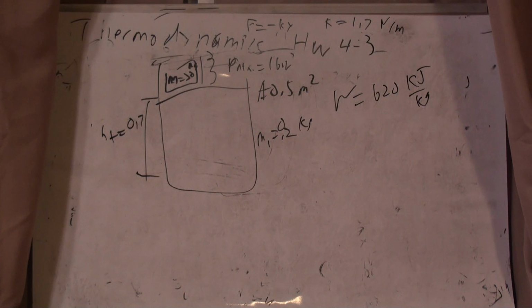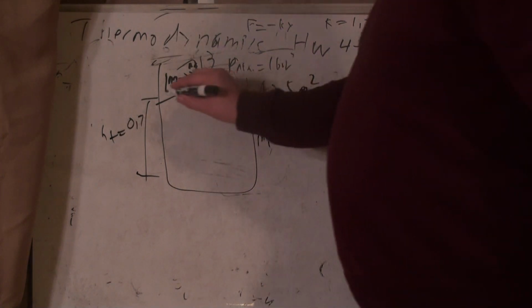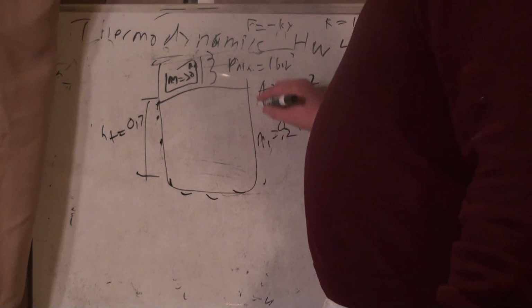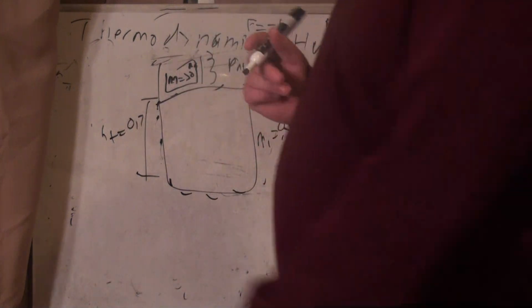Now it says precisely draw the process on a PV diagram, draw the area that represents the work. We could do that, that's part A, but we're really just doing part B. How much heat is transferred during the process? Joules per kilogram. Okay. So I just want to do an energy balance on this thing. I draw my boundary.